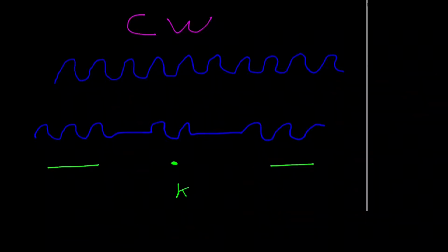So this is a typical carrier wave, the one up here. We're going to call this an unmodulated signal, so UM for unmodulated. This is essentially a signal that's been generated by the oscillator, be it a crystal or a small tank circuit, that is unmodulated. The frequency is not changing, the amplitude isn't changing, nor is the phase changing with respect to time.